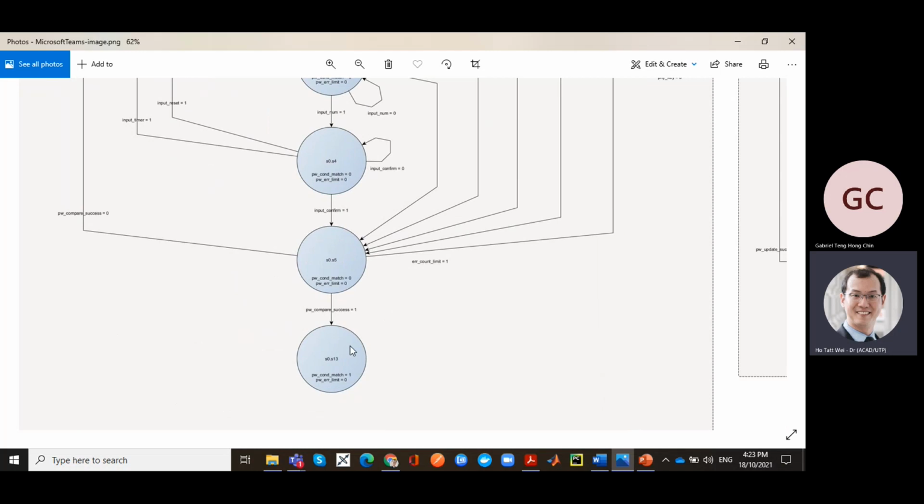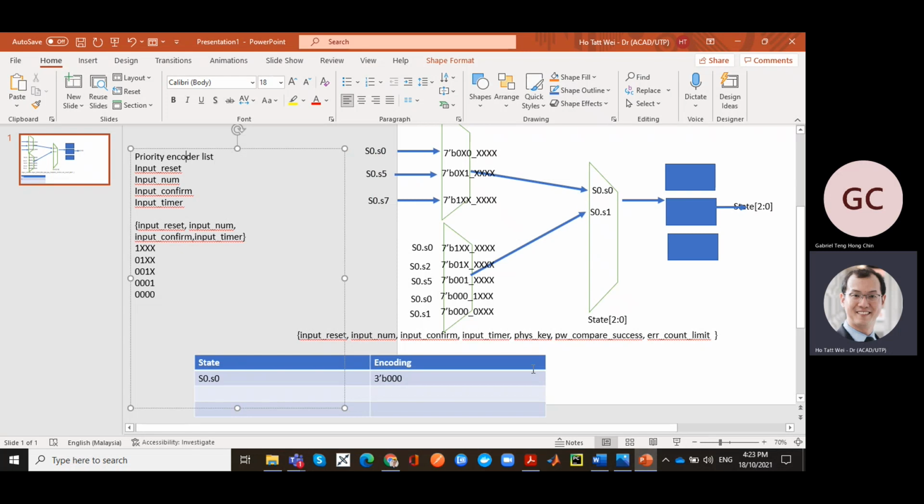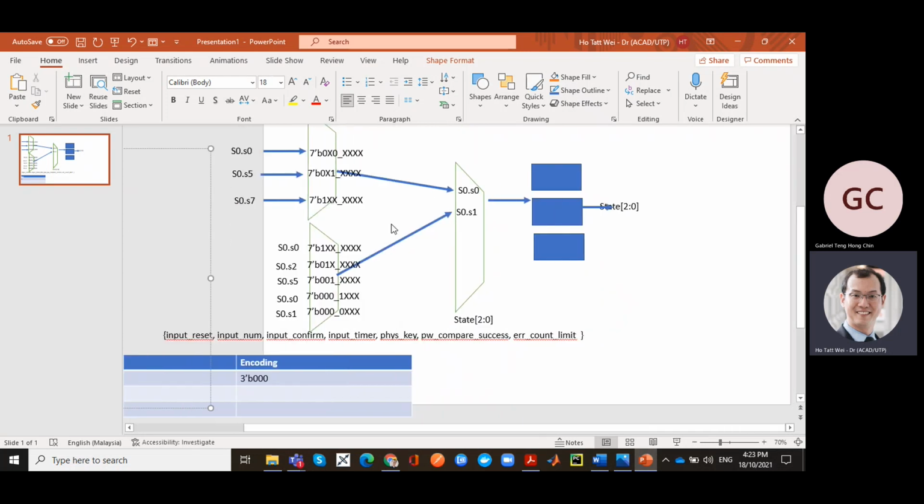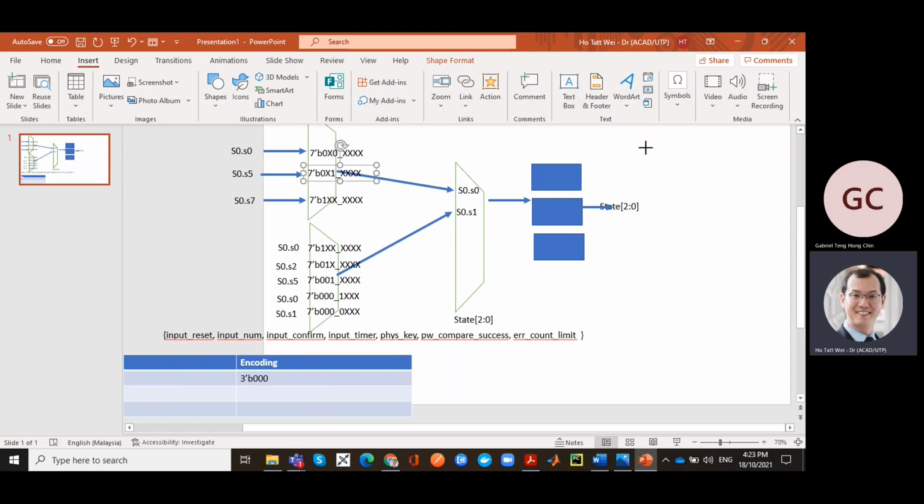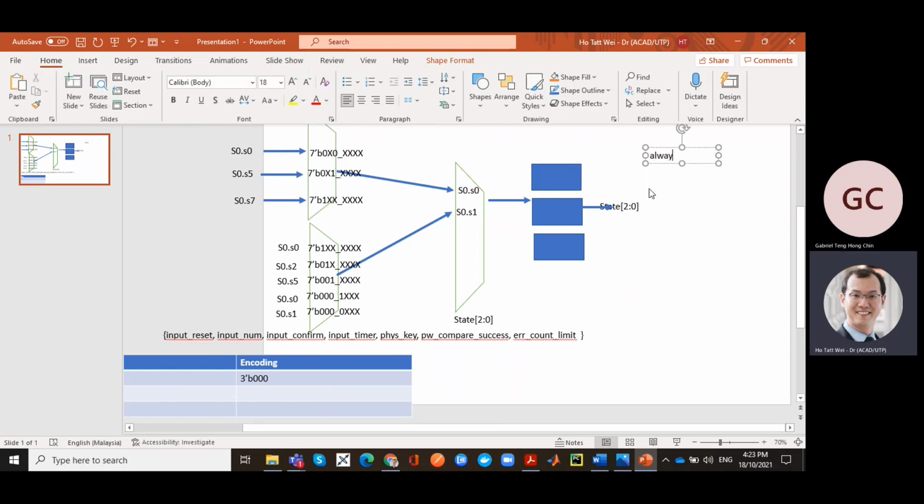Because that's a nice thing about you listing out all the input bit signals for you to transition. Okay, this is just a state machine. We're not talking about how you generate these outputs yet. So based on this, the thing you should understand now is I can write a simple Verilog for this very easily. Because basically my flip-flops always at posedge clock, begin. I apologize, I'm not updated to SystemVerilog. I'm just using the old version, but it still works.